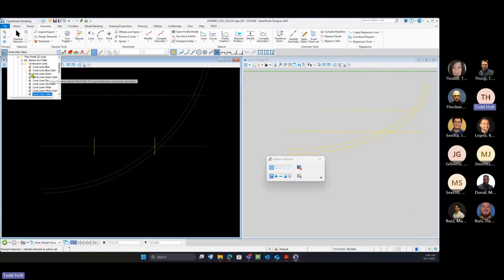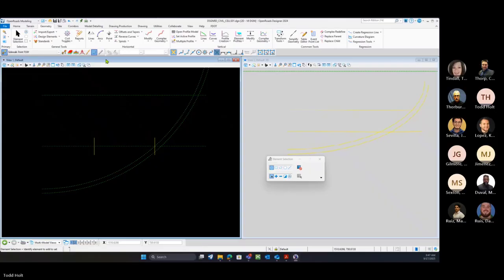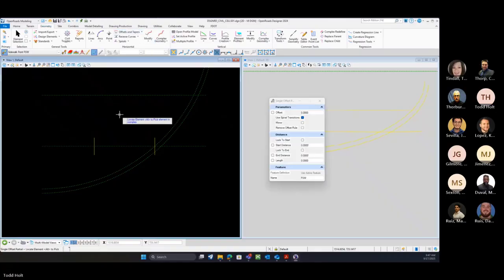I have that rule, and then if I do another sidewalk line, here I'm going to come in and go to our sidewalk. And this is going to be our sidewalk front. I'm going to come in and do a single offset partial. What I usually like to do is set the offset, but I'm not going to set that offset, so I want it to be on this line. I do want to use my intersection snap.